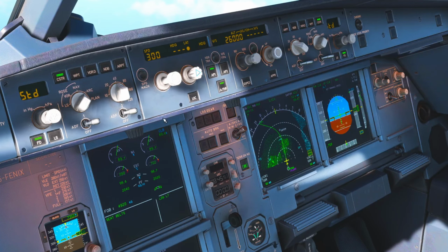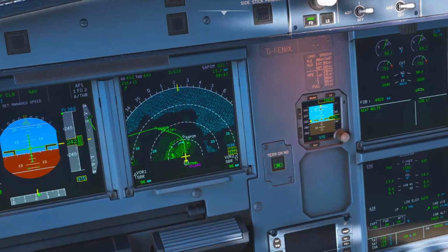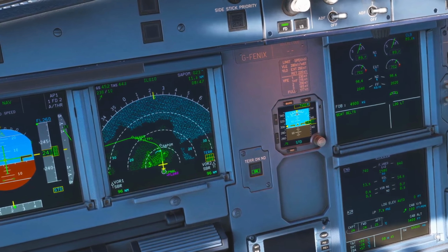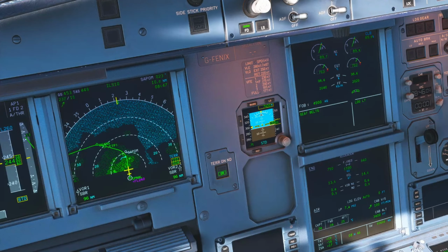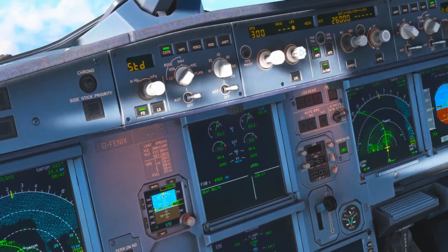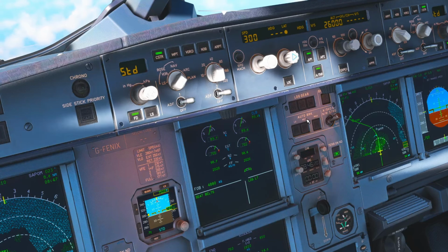For the managed mode, the display shows a magenta color. When a route has been programmed, the pilot can tell the auto flight system to use the route values by pushing the knobs in. Pushing the airspeed knob in will select a managed airspeed, which is automatically adjusted based on economy factors such as aircraft weight, fuel burn, flight duration, as well as constraints on the departure and arrival.